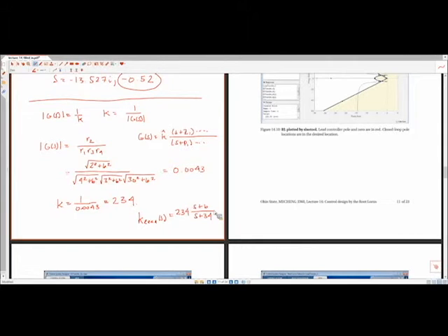Exactly. So the very first thing you always have to concern yourself with is stability, right? And we saw that the locus plot is always in the left half plane. It never goes into the right half plane, so that largely alleviates that fear. We'll talk about margin of stability next week, and so we'll add a little bit more nuance to that statement. But at least if the system behaves perfectly in an ideal manner, it'll never go unstable no matter what your gain is, based off the root locus plot. So this is saying, all right, we care about performance too, which is our metrics on the step response. Let's choose closed loop pole locations to make sure we hit that metric.